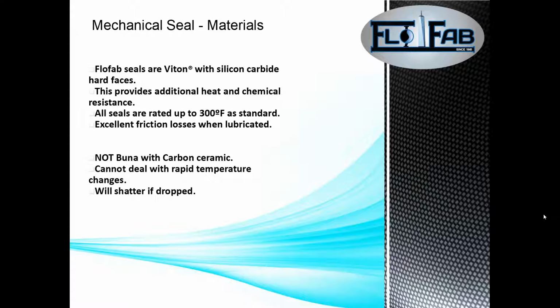Some other mechanical seals that you see that maybe our competitors or some other people use would be, the most common is the Buna with carbon ceramic. There's two problems with this seal. The first being that ceramic doesn't deal great with rapid temperature changes, meaning if you go from not moving to first starting up a pump, right, there's going to be a temperature swing of the ceramic heating up, and over time this can cause the seal to go bad much faster than the silicon carbide.